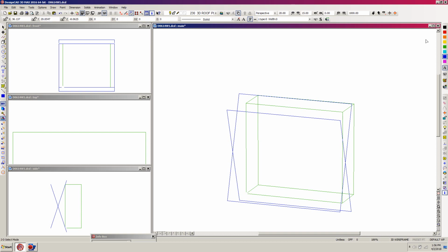But what I'm going to do here is change my color to a red. I'm going to make it that fourth one from the left. It's a bright one, bright red, stands out pretty well. And now I'm going to go over to my RV toolbox, and where it says surface intersection, which is the first one up from the info box little icon, click on that. Surface intersection will show you where surfaces are intersecting, just like it says. Once that command is initiated, you look down in the lower left-hand corner, and it says set one point on each surface.